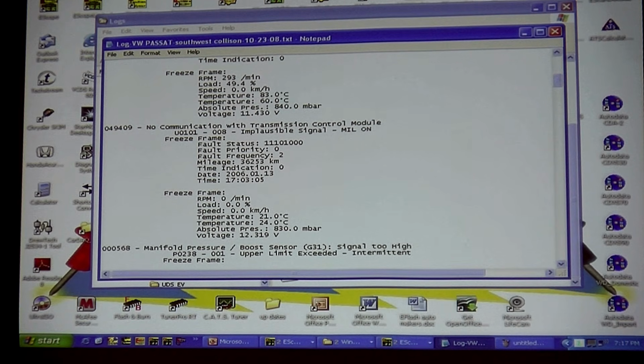When you do these, you're going to get into all of your systems, high and low speed. Some of the clues are on the low speed because the bridge crossed it. I want to see who's got codes, who's not getting data. We're trying to make an assertion here on where my problem really is. And when these things start to fail, guys, you've got codes for everybody. It isn't that you've got one code and, oh, this guy says he's bad. This doesn't work like that. I only wished it did.